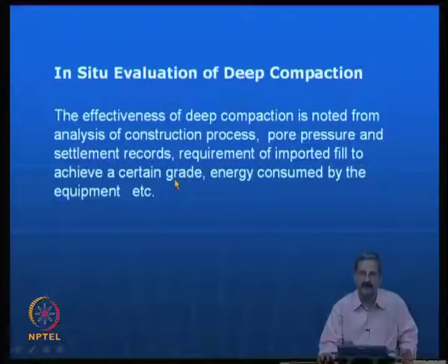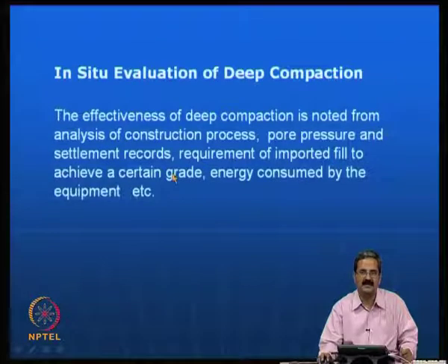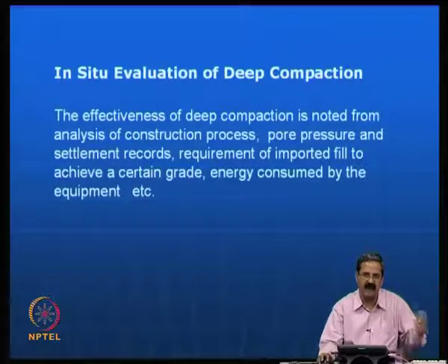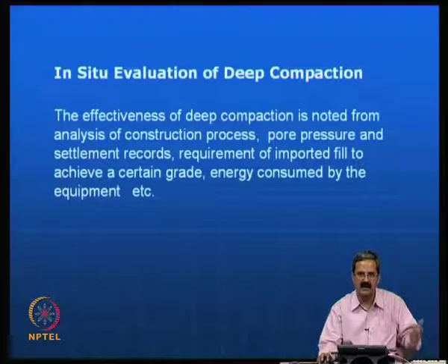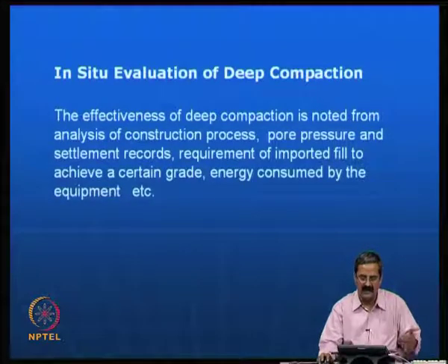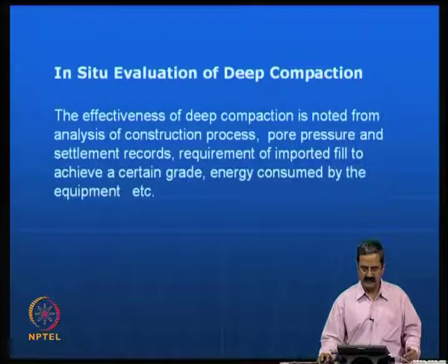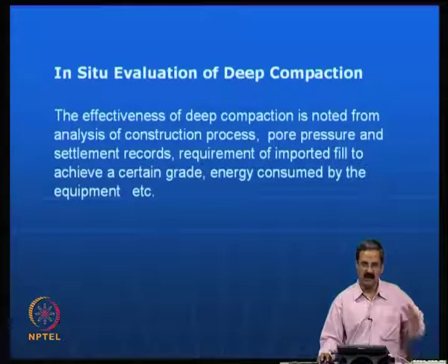Then what we do is consider the requirement of the imported fill to achieve a certain grade. Sometimes in a particular place the whole area is very soft, so you are bringing some other soil from a nearby island, and then you are trying to see that it is densified, because in some places, for example Singapore and other places I just mentioned, you will see some more examples here, you have to get soil from somewhere and start compacting.